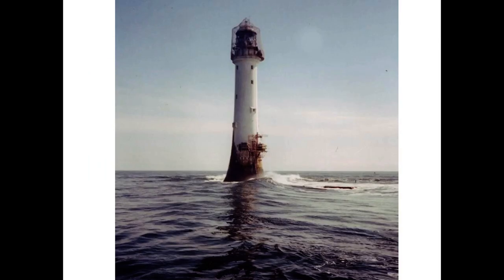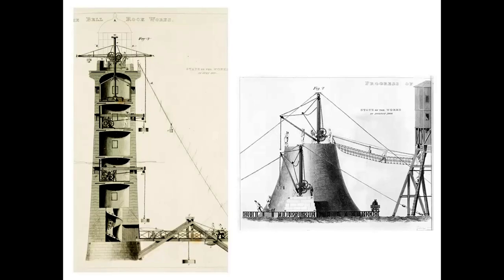So there it is for half of the year. And what he did was they built it there. You can see here there's a temporary structure on the right. They built a timber structure for the workers, and the workers started hammering away at the rock to make a foundation for the structure. So this is a load-bearing stone building, as you can see, and it tapers, of course, because the mass, you need heavier mass down here, gets thinner and thinner as it rises.